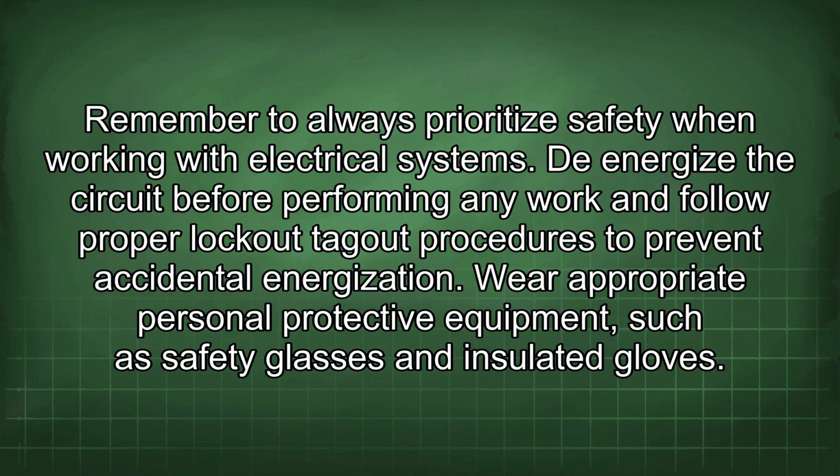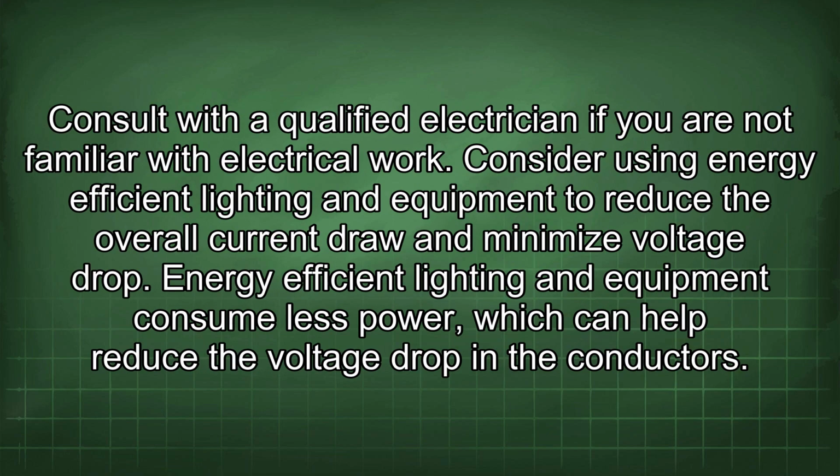Remember to always prioritize safety when working with electrical systems. De-energize the circuit before performing any work and follow proper lockout-tagout procedures to prevent accidental energization. Wear appropriate personal protective equipment, such as safety glasses and insulated gloves. Consult with a qualified electrician if you are not familiar with electrical work.